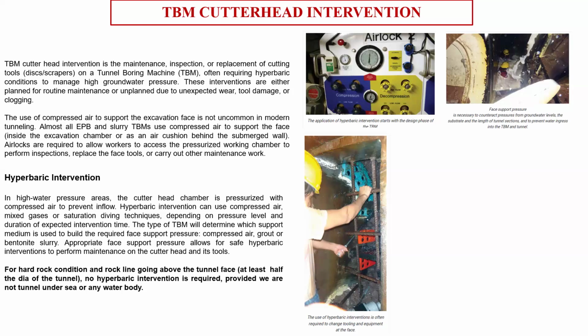But the contractor thinks that in that stage the TBM is passing through a park, so there are no structures. Even if some part of the ground gets disturbed, it will not be a very big problem. It can be managed. But if sensitive structures are lying there, say the TBM is passing through a region where 250, 300 buildings are there, and the ground is not competent, then I cannot apply a very high face pressure. I have to apply a minimum face pressure to keep the face stable, because a very high pressure might affect the foundations of the buildings.